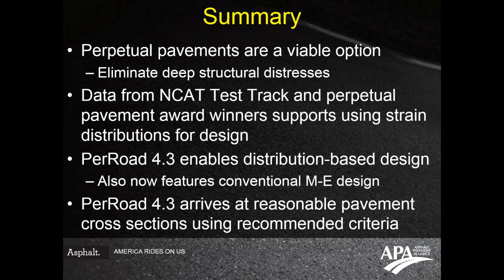The asphalt pavement industry is extremely efficient at dealing with distresses at the top of the pavement structure through night construction, mill and inlay. Those sorts of approaches can be done very efficiently and be very cost effective.